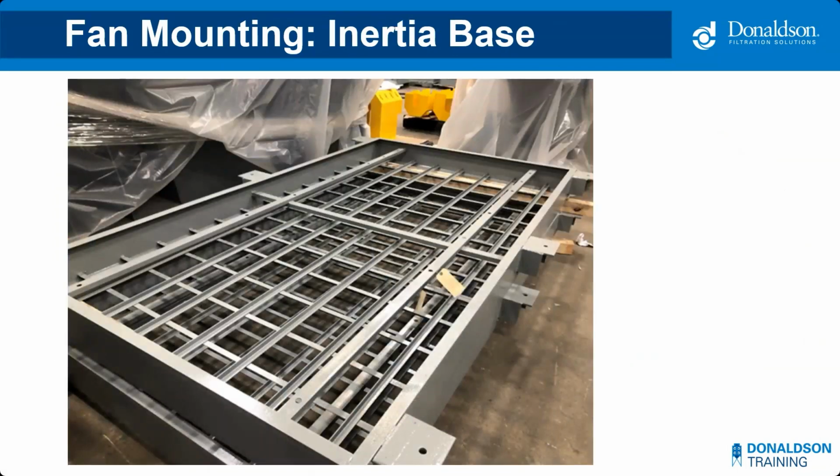This is an example of what we call an inertia base. This is that unitary base, but when the fan is installed, we'll fill this base with concrete and give it that heavy mass, just as if it was bolted to a concrete slab. We can also put these inertia bases on spring isolation. So we could do this up on a structure, fill it with concrete, and use spring isolation to avoid transmitting vibration through a structure.